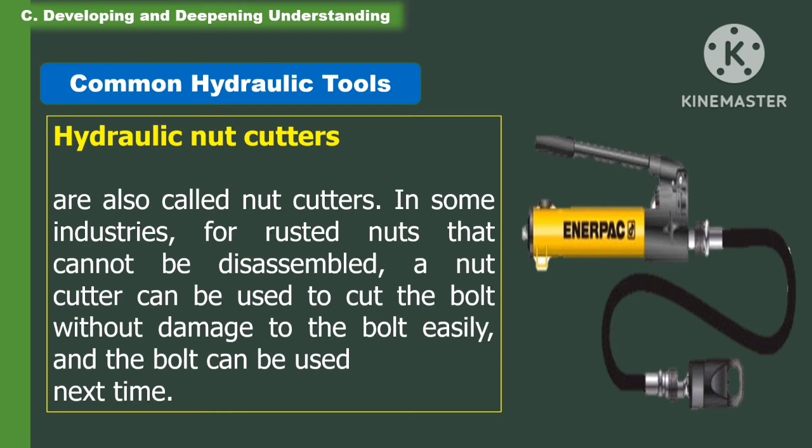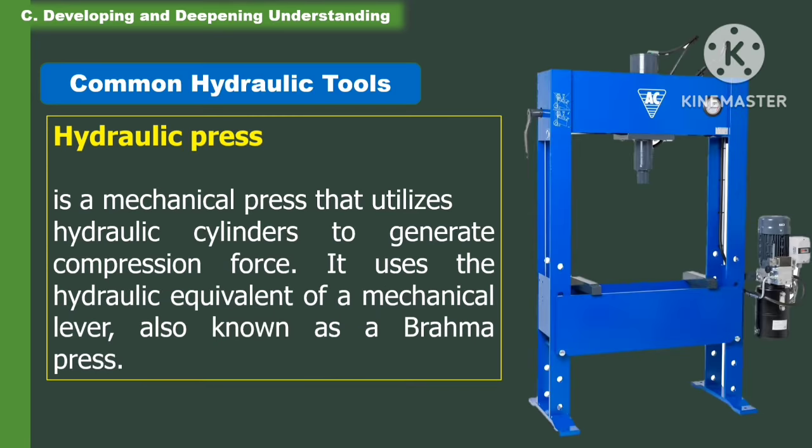Another common example of hydraulic tools is the hydraulic nut cutter, also called the nut splitter. In some industries, for rusted nuts that cannot be disassembled, a nut cutter can be used to cut the nut without damaging the bolt, and the bolt can be used next time.